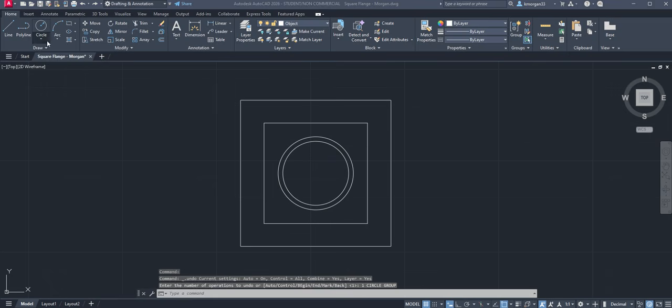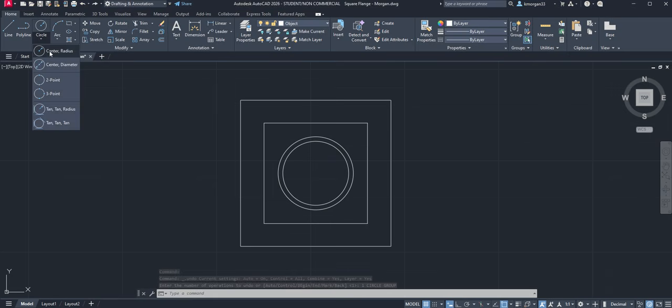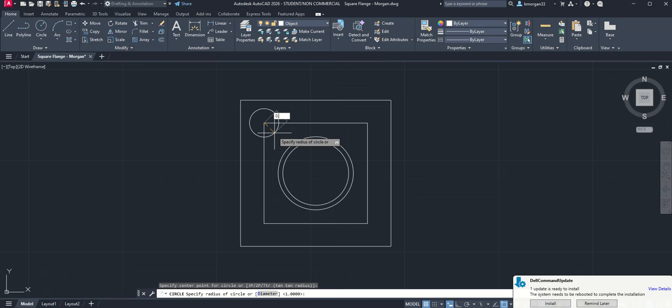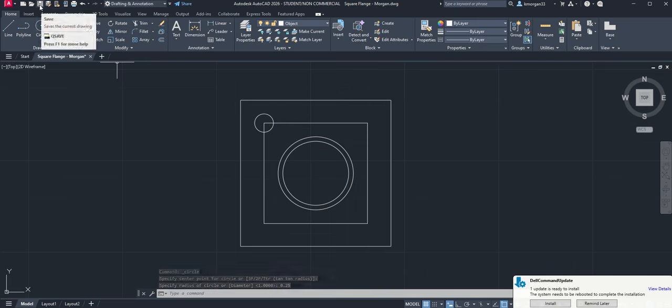The next one is we are going to place a little tiny circle. Let me read what the dimension is. We're going to place it right here. We get the circle, bring our cursor, click on it, and then give it 0.25. Yes, 0.25. Then I'll click and enter. So you will get a circle at the center of that edge of this inner square.